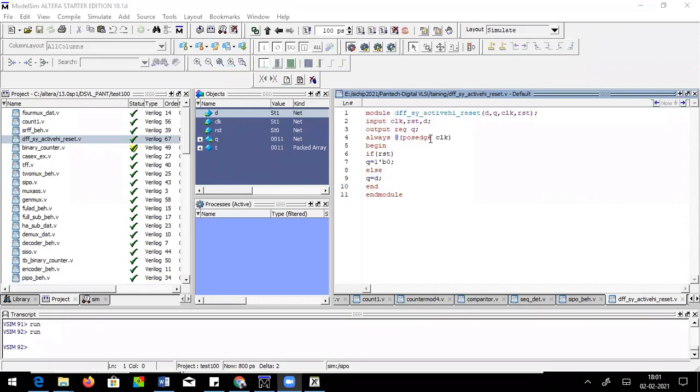When you try to draw the timing diagram, you will understand that though one is capturing during the on period and the other capturing during the off period, the final output will be the one captured during the transition. That's how you build a D flip-flop.